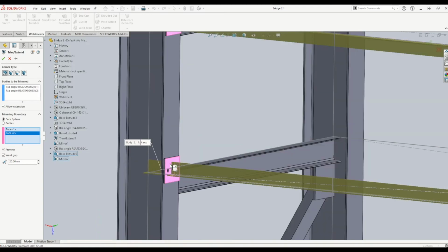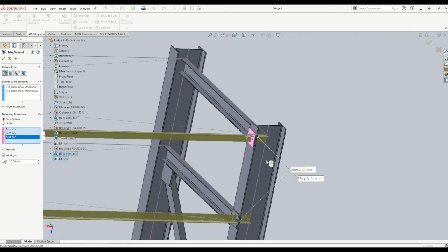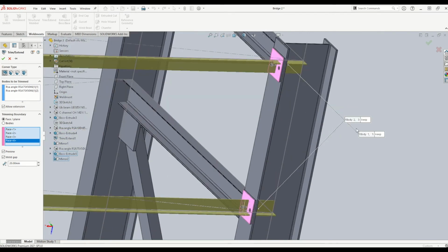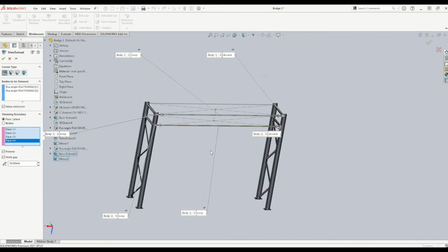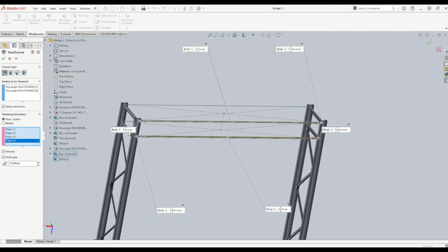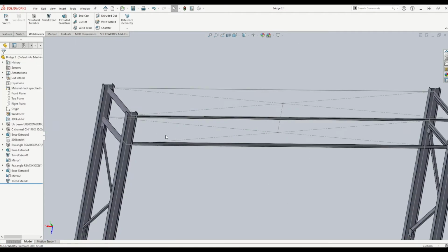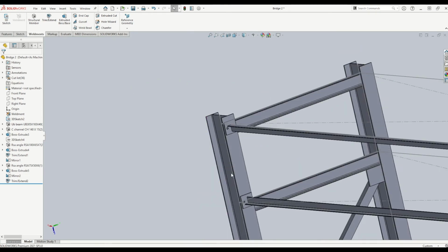Oh yeah, I should be able to actually. So if I select the 4 faces of the plates and select what parts of the strut I want to keep, so I don't want to keep that back edge. So I'll just click, I'm just clicking on this body to make it discarded: left click, keep, discard, discard. So now I'll tick that. So now I have my cross members with the plates to weld on.